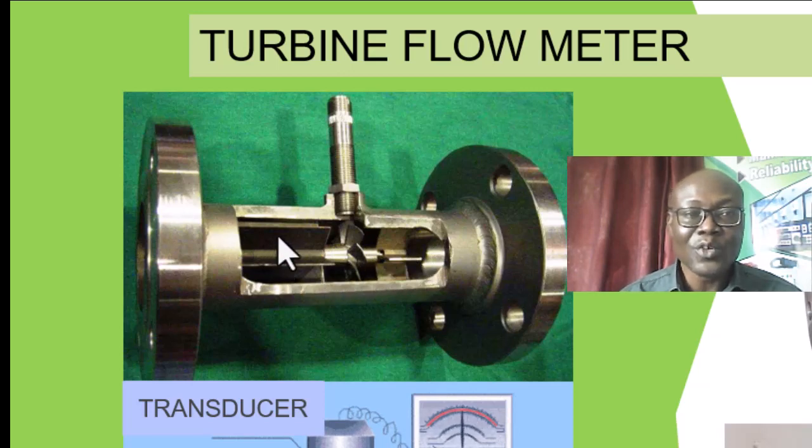Okay, so this is the flow conditioner to help us have as much as possible laminar flow, directing the fluid onto the blade. Are we getting it? So between these two blades, a specific volume would have passed this section of the flow meter. So what this is, is a pulse counter, okay?